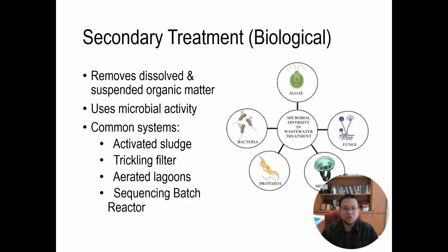Secondary treatment is where the magic of biology happens. The primary effluent, though clearer, still contains fine colloidal matter and dissolved organic contaminants. This stage is designed to remove these pollutants using living organisms, primarily bacteria and protozoa. The microorganisms feed on the organic matter, converting it into cell tissue, water, and gases like carbon dioxide. This process drastically reduces the BOD.